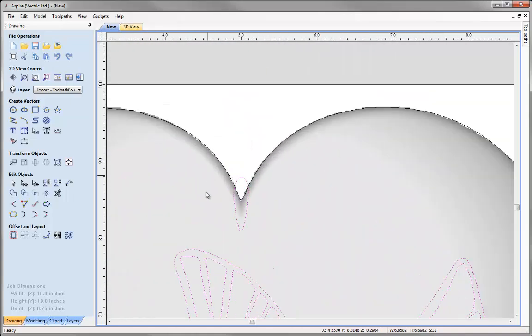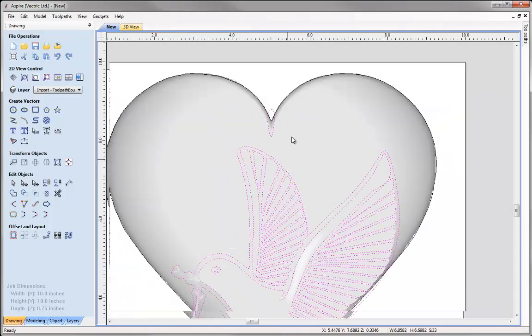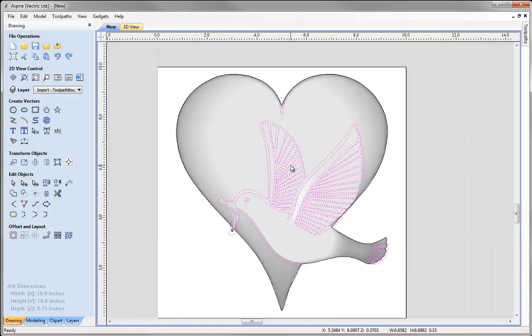And then we've just created a tiny vector here just to accommodate the top of the heart where the two peaks join as well. So these are the most optimized vectors for this particular model. You would obviously need to balance the time between creating or editing the vectors to such an extent within your own work. So that's where we need to start thinking about balancing how much effort we put into 3D machining efficiently, compared to, say, perhaps just running the smaller tool to begin with, or using vectors that aren't so optimized like the ones that we've got here.